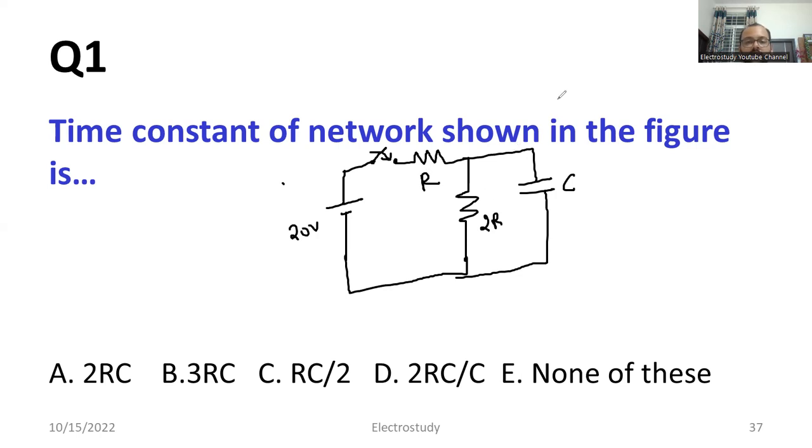So you know what is time constant. Time constant, tau is equal to R into C, right? RC, that is the general equation. Here, when the switch is closed, what is going to happen? What about the value of resistance here? The internal resistance. When the switch is closed, the internal resistance of the source also becomes 0. We consider R is equal to 0. Now I'll be drawing like this. Here we have R. You don't mark anything here.